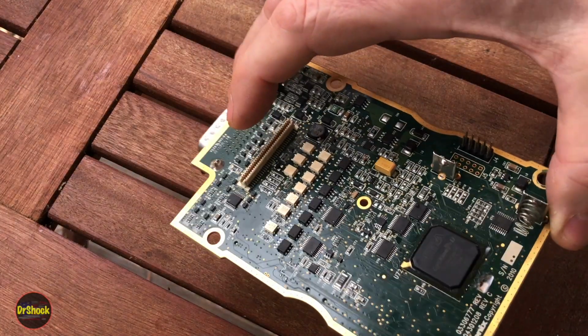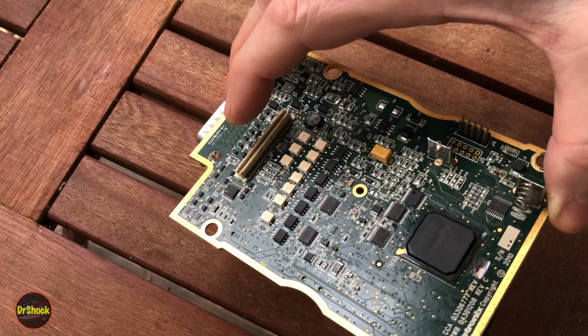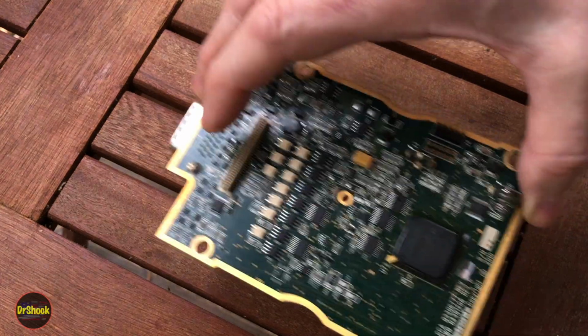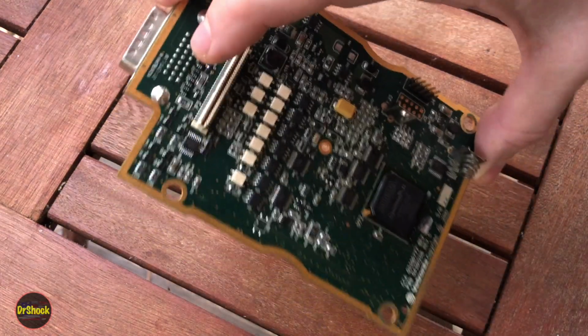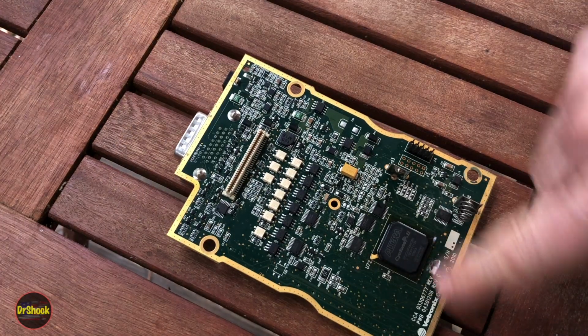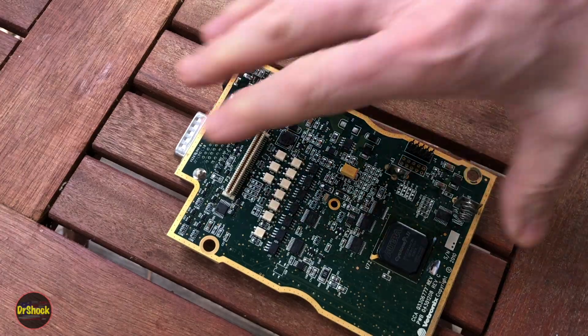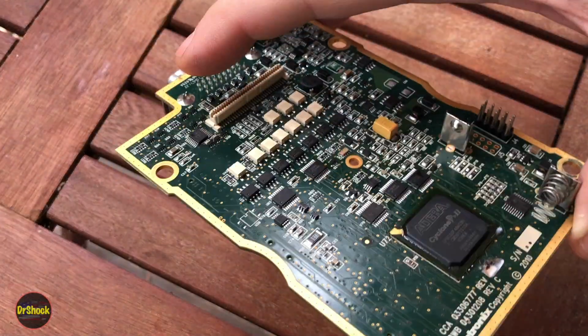If I did this over again, I think what I would do is let the heat soak a little bit longer at around 185 degrees. I would try to raise it up at more of an angle and try to work all that underfill, let it run out before we actually tried to liquefy the solder. So if I had another shot, that's the technique I would try.